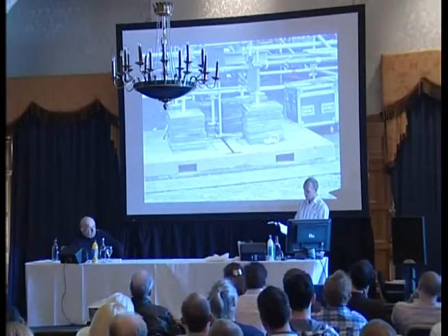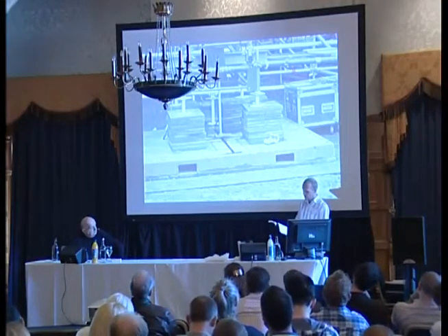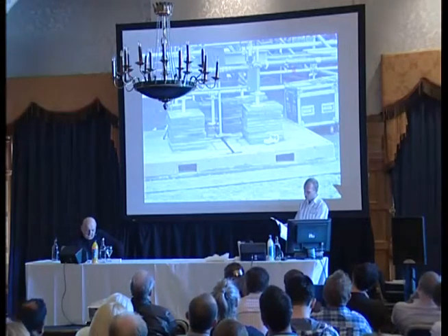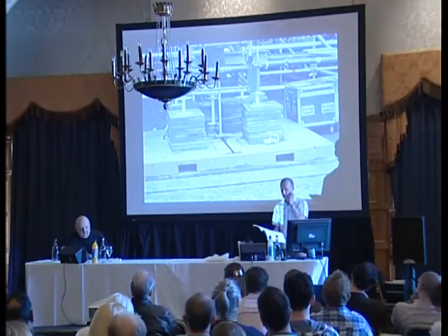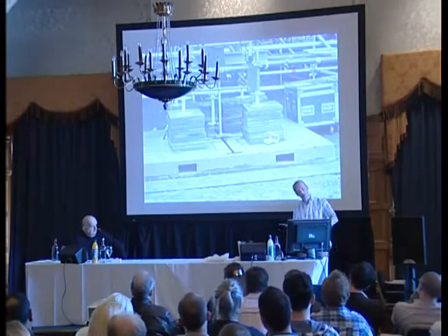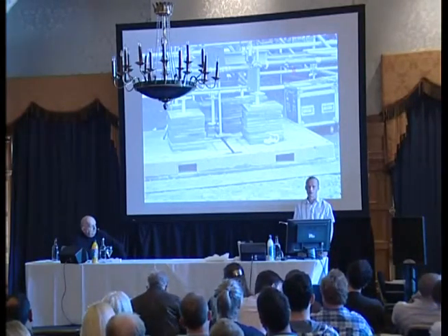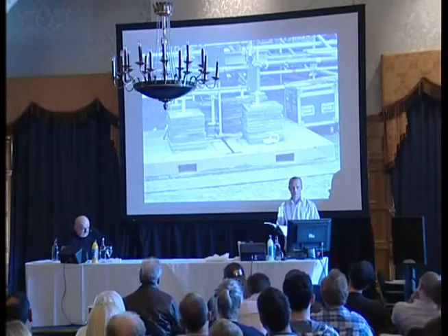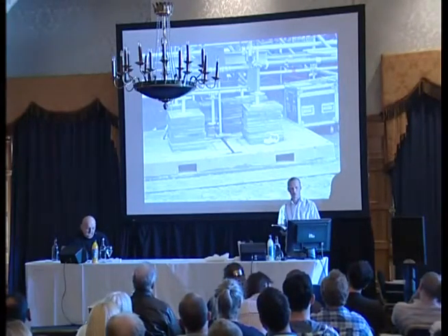I can't even read it, the print is so small. Client's requirements, site location and event, design. So it's the client's responsibility to measure the ground bearing capacity. So if you're the supplier, you should be asking that question of your client. Say, what ground is it on? What's the ground load bearing pressure?